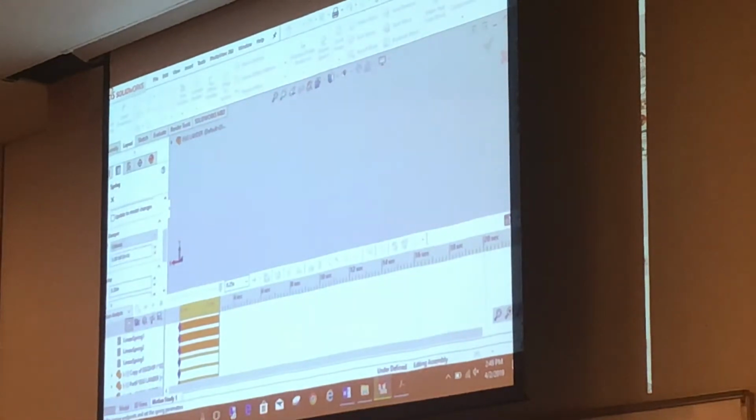So I can click the check mark next to the damper box, and again, you can do linear or nonlinear damping. And I'm just going to give it a value of 0.05. Okay. So, let's see. We said just a moment ago that for a spring, F is equal to Kx, right? Force is a spring constant times the displacement.